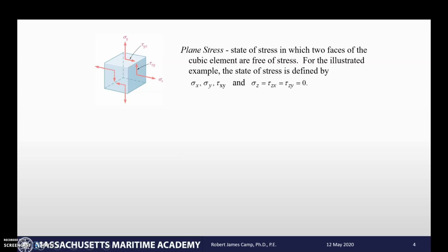So basically we knock out a lot of the stresses, and we're just going to have a normal in the x, a normal in the y, and a shear stress in the xy. This is a pretty important thing when it comes to what we call continuum mechanics, which is basically just strength of materials and mechanics, anything where we're dealing with forces. A material is under plane stress when we have that 0 and we're only dealing with a couple of these vectors. So the stress analysis is considerably simplified, because we're only looking at 2 normal forces and a shear force.